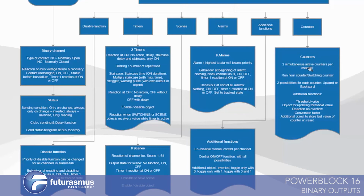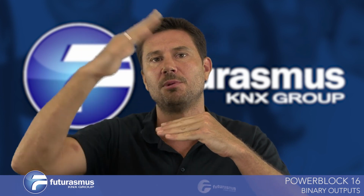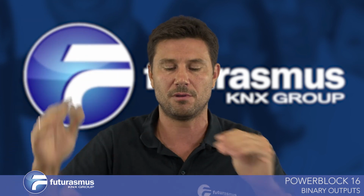So if you know the bulb is very close to its lifespan, you change it, even though it's still working. You change it because it's much cheaper to change the bulb than having to come each time to change the different bulbs one by one. So this is a very interesting function also, the run hour function. Then there's also a switching counter, which counts the number of switches. You can decide whether it counts when it switches on, when it switches off, or both on and off.